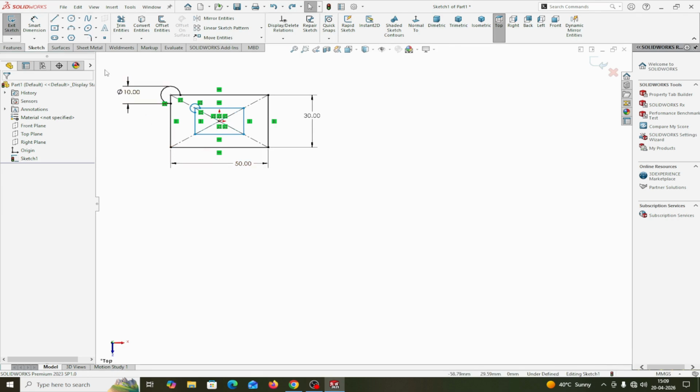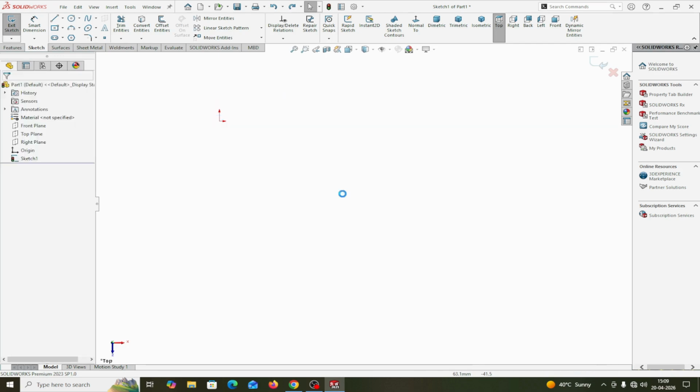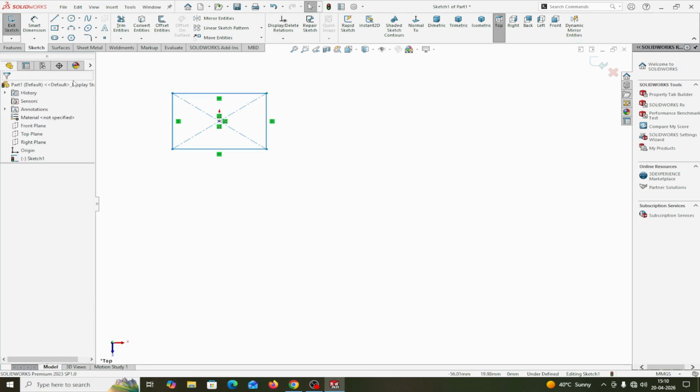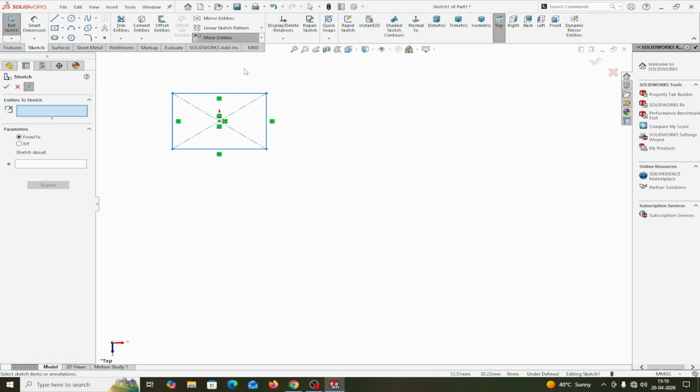Now select it, delete it. Now I make another sketch, and suppose I take this one, stretch entities. Okay, in the stretch entities, select this one. In this stretch entities, you have to select by crossing window.